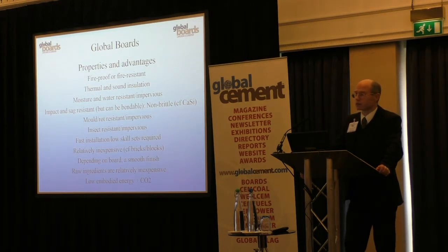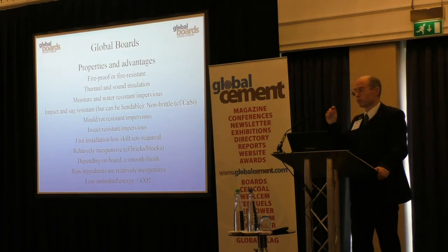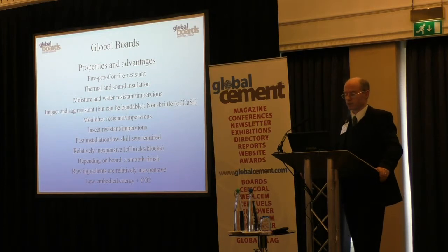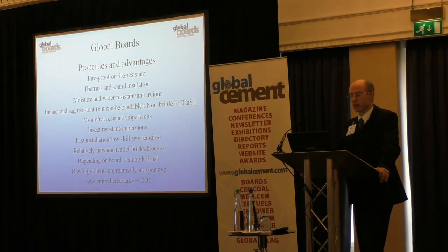Now I wanted to mention briefly some of the properties and advantages of cement-based boards and compare them and partly contrast them to the properties of gypsum-based boards. So cement-based boards, obviously fireproof and fire resistant. They have good thermal and sound insulation properties. They are, and I think this is really one of their prime advantages, completely moisture and water resistant or impervious. So you can put them in water for a year and essentially their properties are pretty much unchanged. The same cannot be said for most types of gypsum wallboard.